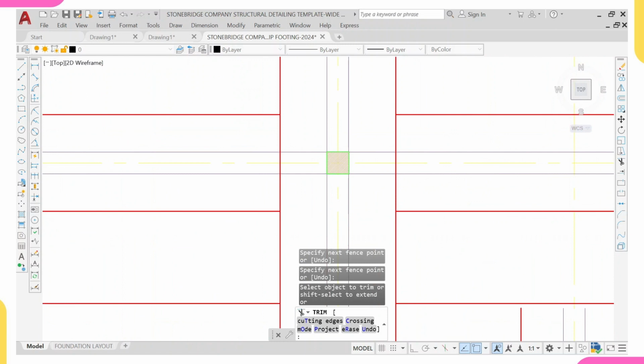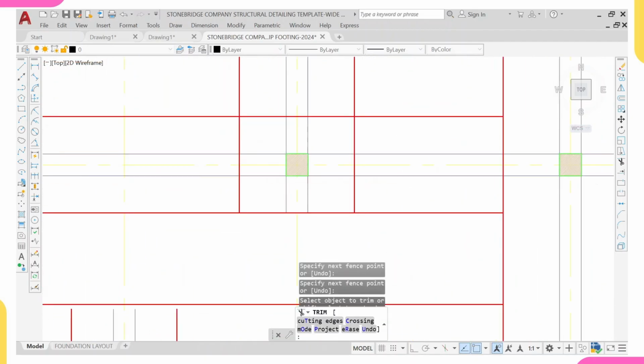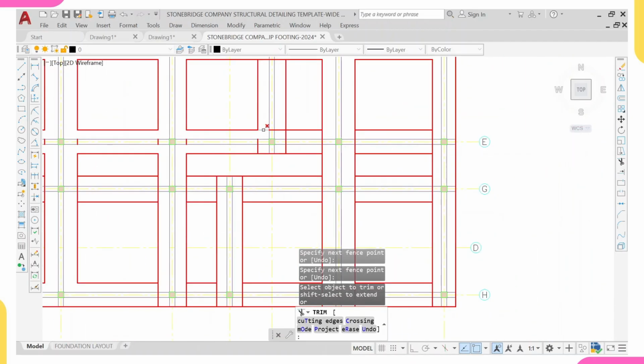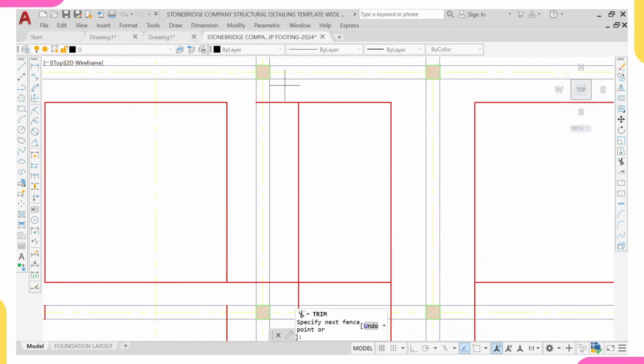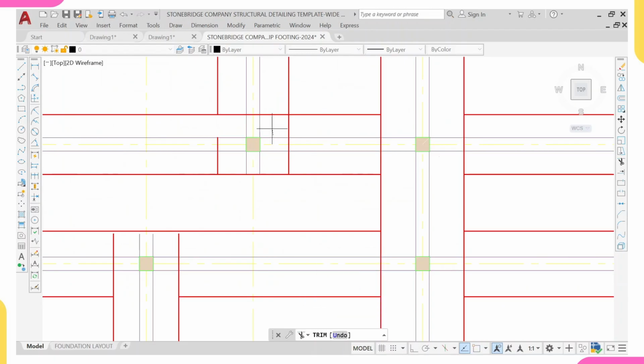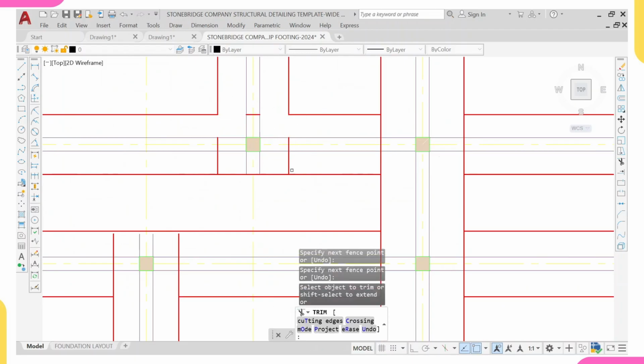So when I checked strip foundation, it's passing very well, everything is okay. So that's why we now resort to using strip foundation. Assuming strip foundation failed, I did not do the vertical of this one, so let me just do it at the same time. Assuming strip foundation failed, you could have moved over to beam raft foundation, and if beam raft foundation should also fail, we'll move over to slab raft.